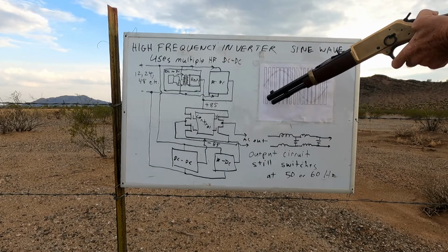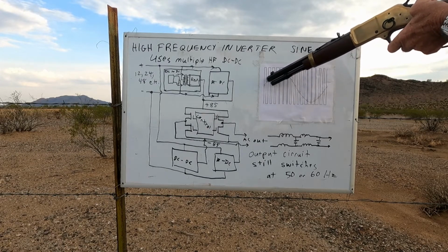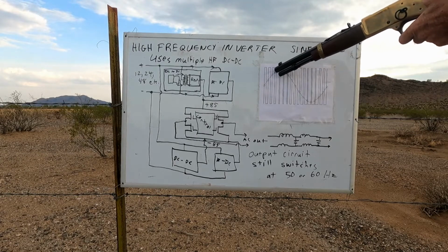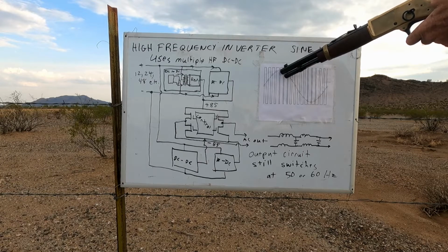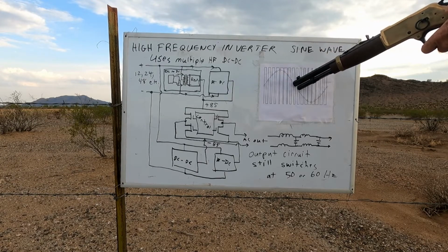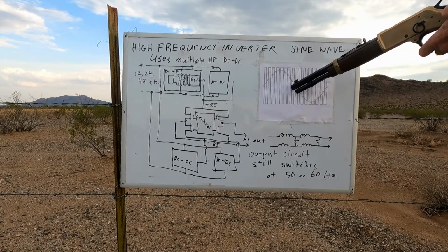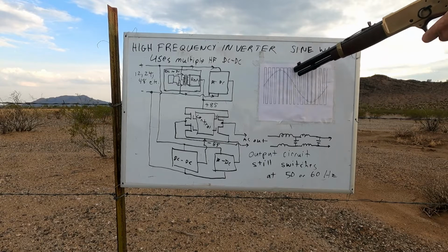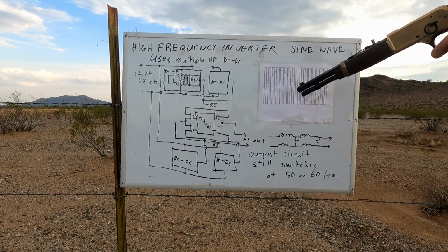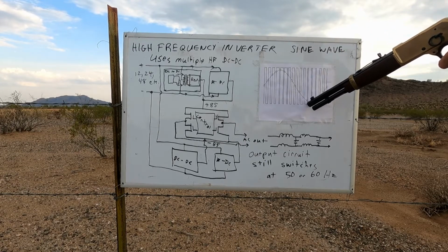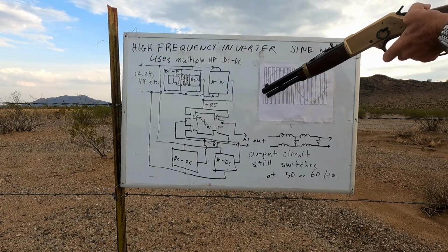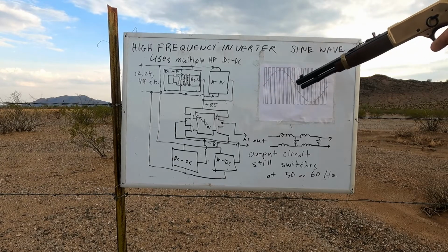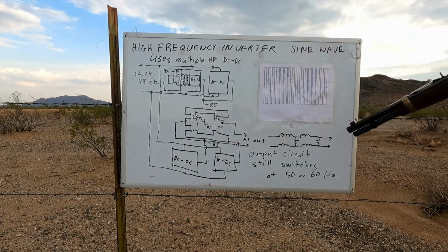And the way that they create the sine wave is that during the positive intervals, you'll see that the switching spends a lot of time on the positive half. And as we swing more and more negative, you can see it's spending less time in the positive. And right around zero, it's about 50-50. You spend equal time high and equal time low. And when you go negative, you see that you're spending a lot of time in the negative region. So when you filter and take the average of these pulses over time, they can be shaped back into a sine wave.